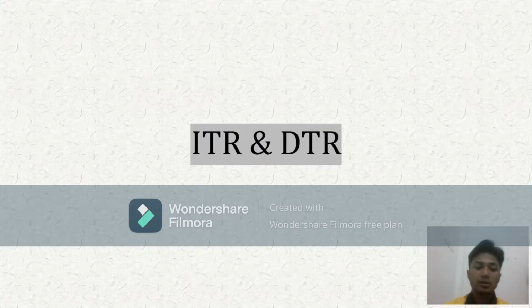ITR is known as the inverse time relay, and it has an operating time depending on the magnitude of current. Generally, with inverse characteristics, the operating time of the relay is smaller as the current gets larger. This relay has two settings, which are pickup current and curve type. It is slow to trip at low current and faster to trip at high fault currents.